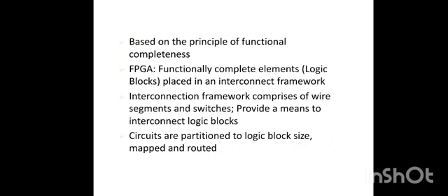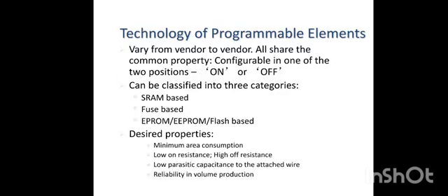It is based on the principle of functional complexities, FPGA, that is functionally complete elements placed in an interconnect framework. The interconnection framework comprises wire segments and switches that provide a means to interconnect logic blocks. Circuits are partitioned into logic block size, mapped and routed.